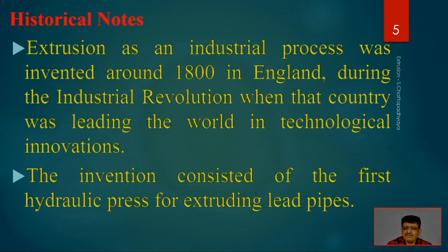The biggest advantage of the hydraulic press is that it can give stepless, non-jerky, smooth and blunt forces. Not very fast, but smooth, stepless, non-jerky. And this is very much required in extrusion. It has to be uniform and stepless force, which sometimes cannot easily be done by electric drives. So that is why hydraulic is best suited to press, whenever the pressure is exorbitantly high.